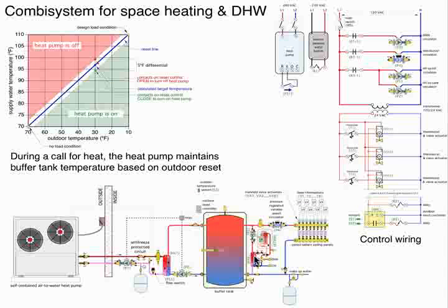Now, the temperature rise we get will depend on the temperature in the tank. If the tank was up at 120 degrees, and this was a generously sized heat exchanger, we might come out of here at 110 degrees. If the tank is only at 85 degrees, obviously we aren't going to come out of that heat exchanger anywhere near the temperature we need to deliver to the fixtures. So we're going through a small thermostatically controlled electric tankless water heater. And that'll provide the boost. The modern versions of these are set up with thermostatic controls. They will only operate the heating elements at the wattage necessary to take whatever preheated water temperature comes in and boost it up to that desired set point temperature.